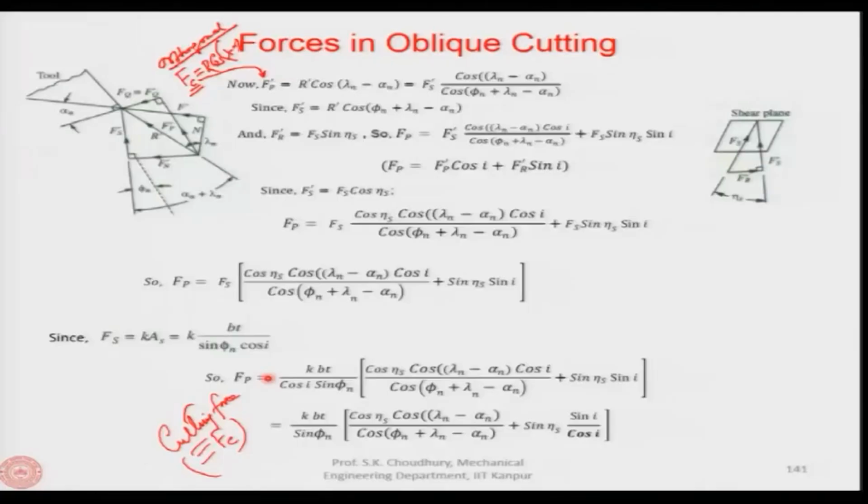Therefore, the forces are coming in all three axes, and we have to resolve the resultant force into different planes, particularly in the plane normal to the cutting edge. So, we will look at this slide. For example, here we have determined analytically the cutting force, Fp. This is the cutting force along the cutting velocity vector, and this Fp is equivalent to the cutting force in the orthogonal cutting, we said.